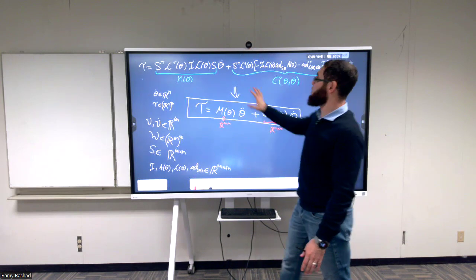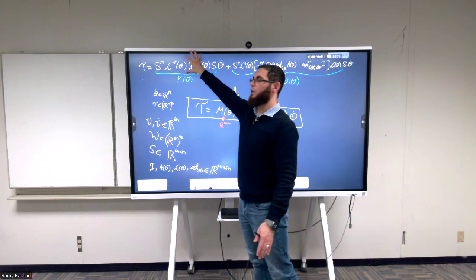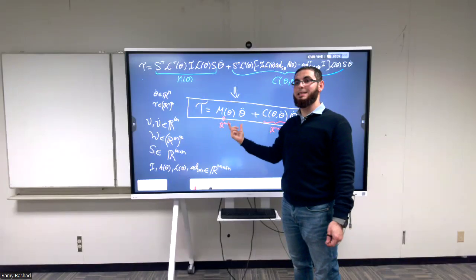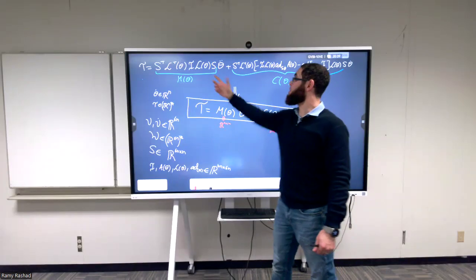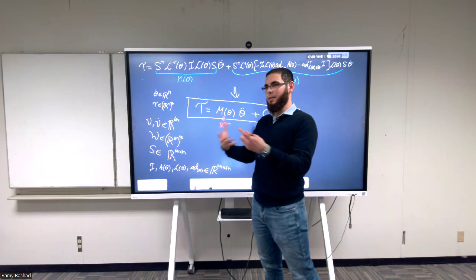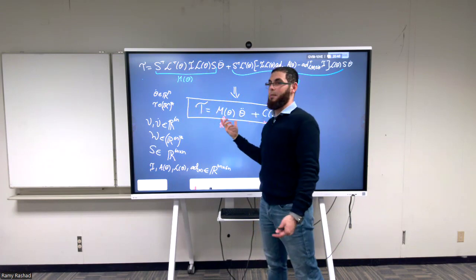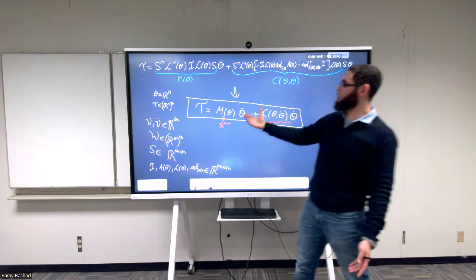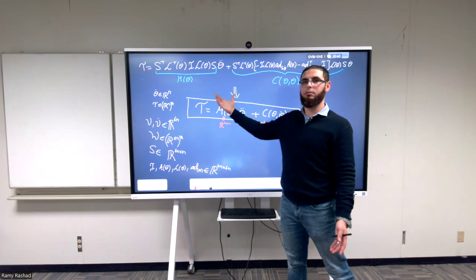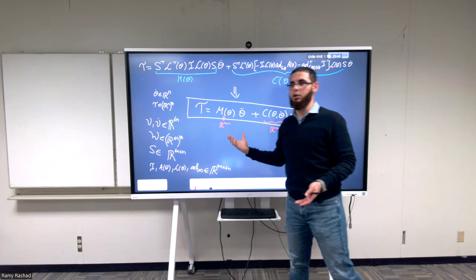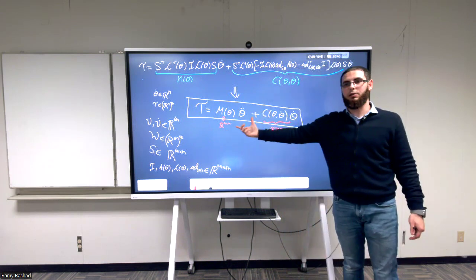So in the end, you see we have here a transformation that transformed this inertia tensor to put it in a new form that's n by n. But it's the same thing in the end. This was the inertia tensor that makes the kinetic energy. And in the end, the M here is just its reduced form. What I'm trying to say is that these are the same expression. So this one and this one, they're of the same nature. This is inertia. This is also inertia. This is why it's called the mass matrix.